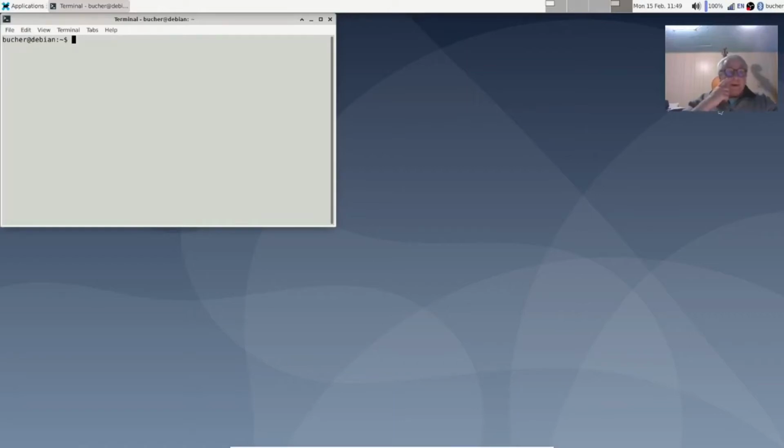In this example, I'm going to use pysimCoder in order to generate a NuttX code from a block diagram. In this block diagram, I read an analog signal from the ADC pin of my STM32 card and send the signal to a real-time plot. I open pysimCoder.